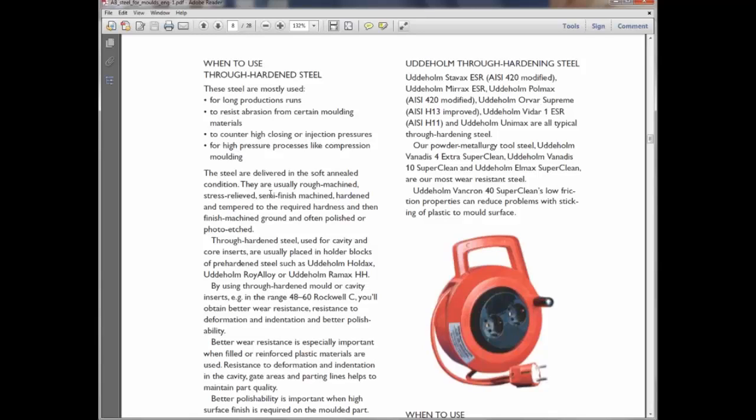Many residual stresses are generated inside the material of the mold, because the cutter is rotating at around 1400 or 1500 rpm and we are taking very big depth of cuts. Because of that, many residual stresses remain after the rough machining.